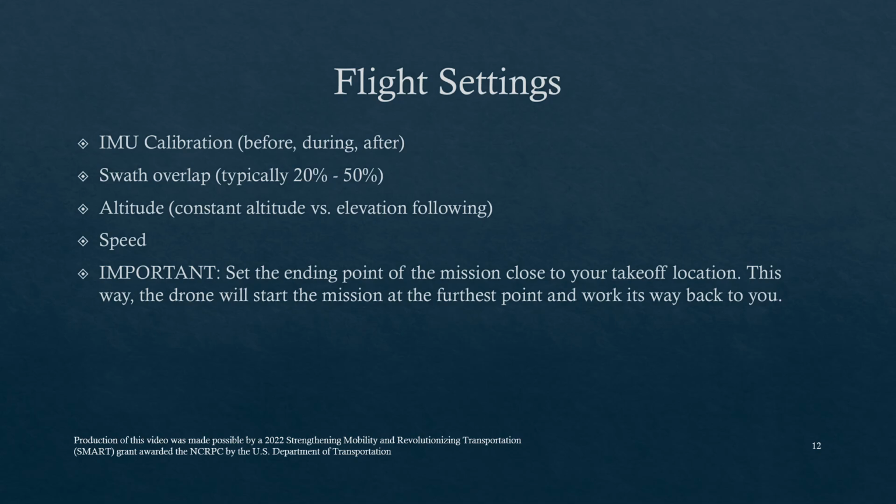So typically this is 20 to 50%. Really never a reason to go more than that, because again, these point clouds are so dense already. And comparing to manned aircraft LiDAR, a lot of those standards I was talking about are typically used to dealing with 8 to 10 points per square meter, where drone-based LiDAR is sometimes producing hundreds of points per square meter, which ultimately is too much data that ends up getting filtered out anyways.